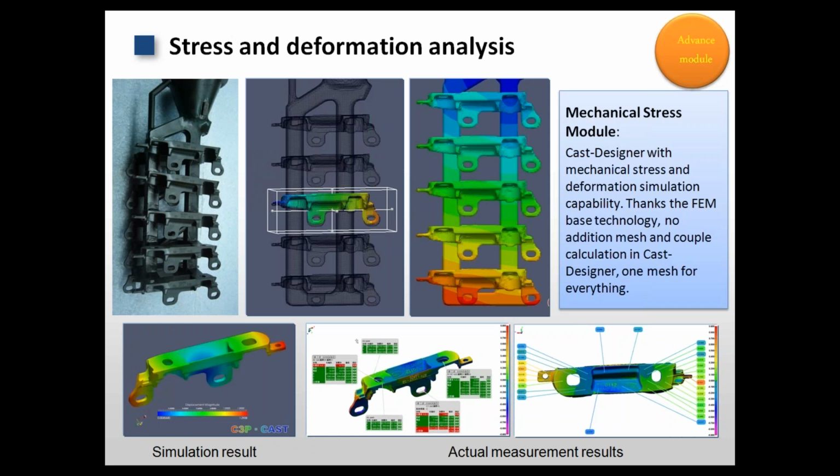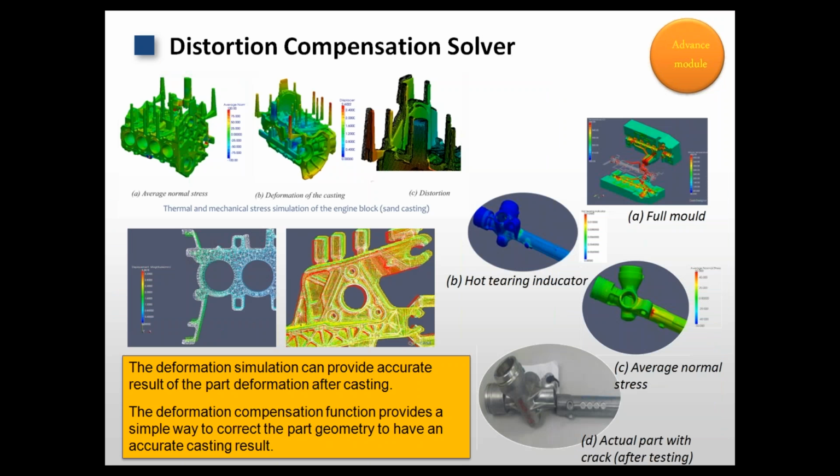And this is another case in the investment casting industry, the stress and deformation analysis. Now let's take a look at the distortion compensation solver. This solver is based on the stress module, because you must first have a simulation round of the deformation, and then you can make the compensation.